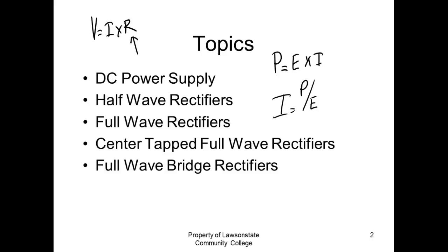So that means, okay, if my wire has resistance, and I want it to drop a smaller voltage, then I want it to drop less. Now the wire gauge has nothing to do with voltage. What does a wire do? What does a conductor do? The actual conductor, what's its function in life? Conducts what? Current. Conducts current, right? You'll understand that. So the wire gauge determines how much current it conducts. Not how much voltage you apply to it, but how much current it conducts.